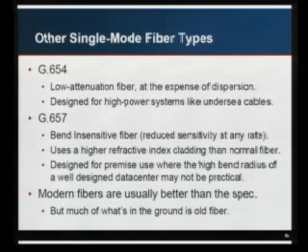The other types, there's specific special low attenuation fiber that's used for undersea cables, where maybe you don't care about dispersion so much because you can fix it with dispersion compensating fiber, but you really care about the placement of your undersea amps, because these cost millions of dollars. So it's specifically engineered to be very low dispersion, very low attenuation.